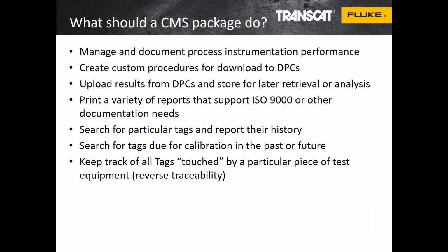So what should a calibration management software package do? We should manage and document the process instrumentation's performance, be able to create procedures for download to documenting process calibrators, or if not working with a documenting process calibrator, print a method sheet for manual documentation, upload results from documenting process calibrators, store for later retrieval or analysis, and print reports to support ISO 9000 or other documentation needs.